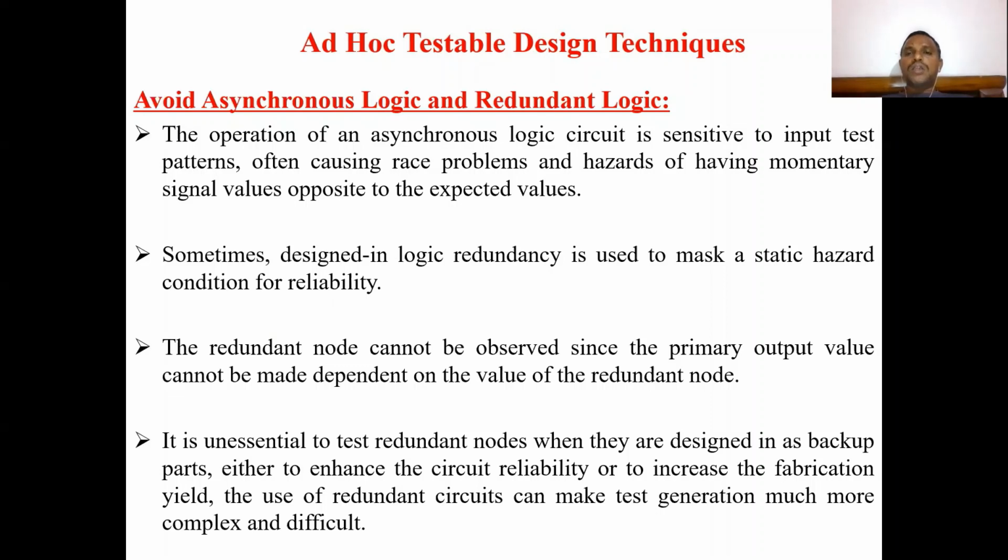If the output is not the same as the expected value, that type of problem we call hazards. Sometimes, designed-in logic redundancy is used to mask a static hazard condition for reliability. Designed-in logic redundancy is nothing but repetition of the circuit; repetition of the gates is called redundancy. Sometimes, to handle the static hazard condition for reliability, we use this logic redundancy.